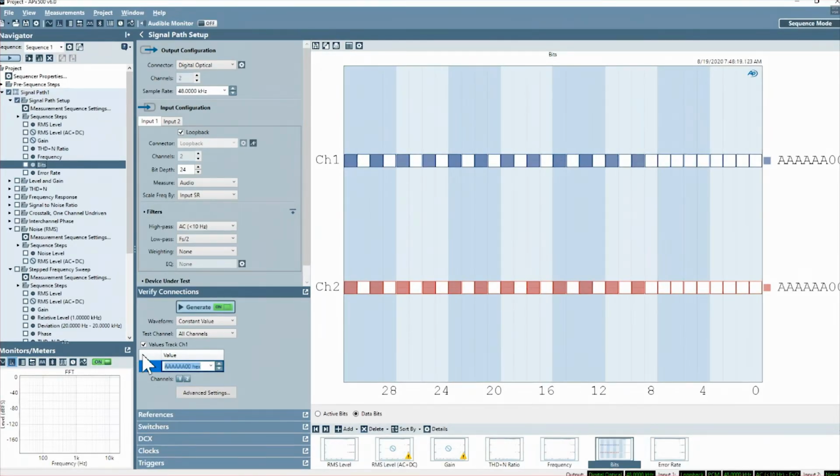This is just a very simple data pattern. If I was looking at this on an oscilloscope, I'd directly see the high and low bits of the actual data word. And if data was getting mangled, I'd see that right away. So this just generates a constant pattern for the digital word. It's really not audio data at all.